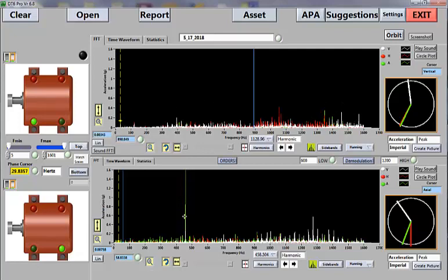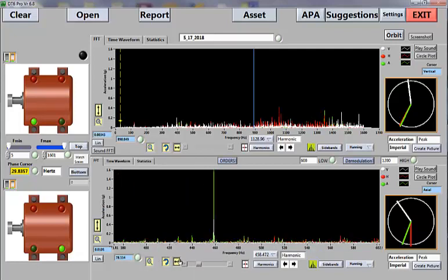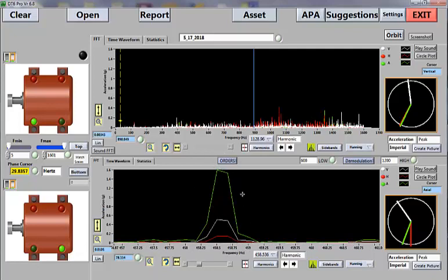This vibration here at, let's see what it is, 454, seems to be really resonant. It's unusually high, so there's probably a resonance going on right there. And from the looks of it, if we zoom in, it seems to only really be affecting the axial and the vertical. So chances are there's a resonance that's slightly off angle between the axial and the vertical. So that might be something to look at.